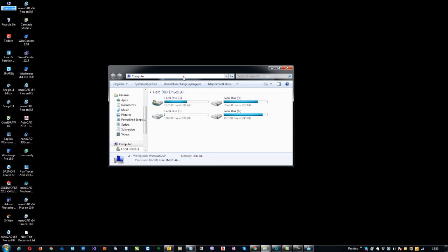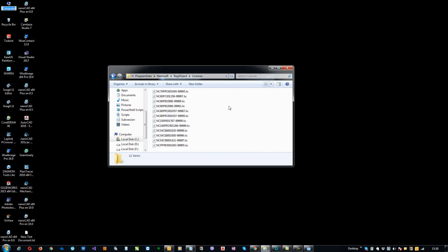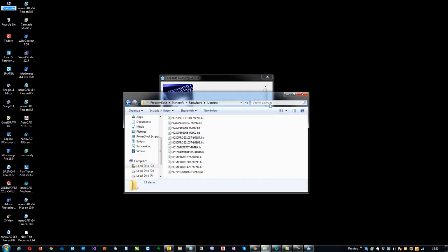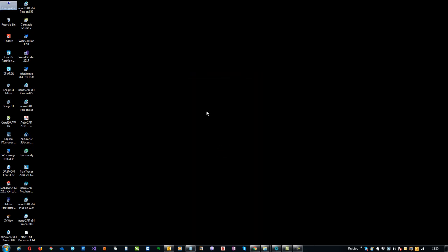So I'll click and say I would like to go to this location, so I should receive my license in this directory. The nanoCAD server will drop a license file to this directory. This is fine. Now I should go to next and finish the installation and activation process. So I'm done with the installation process and the activation.